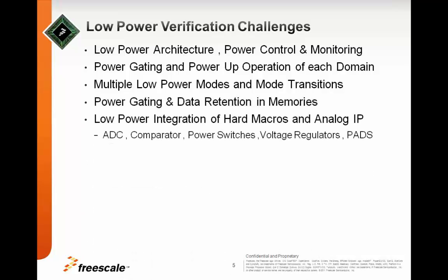The low power automotive SoCs have a significant amount of analog content, like the on-chip voltage regulators, power switches, and precision ADCs and DACs, etc., which significantly adds to the verification challenge to verify the digital-analog interface as well as the low power operation of the analog hard macros.